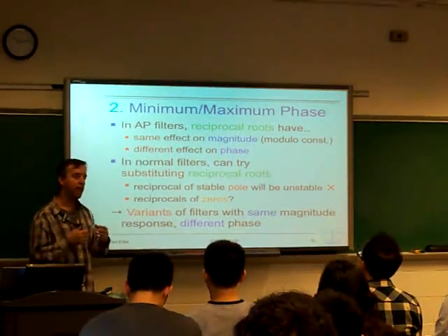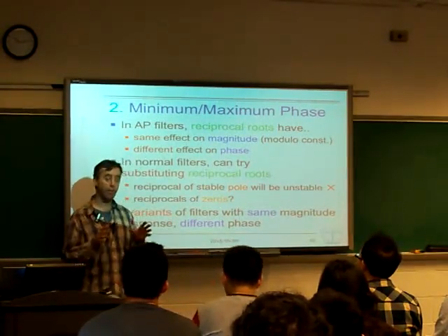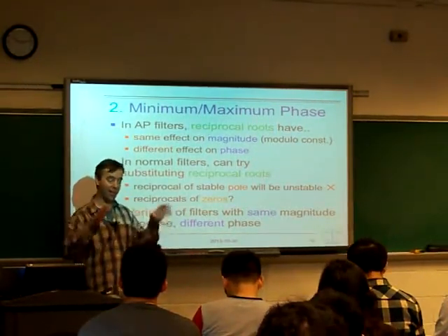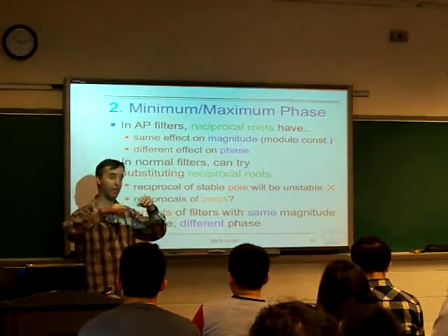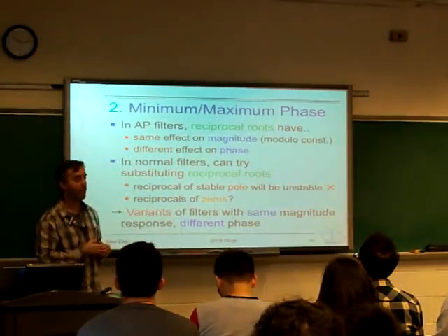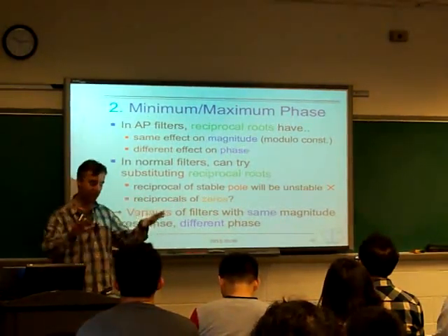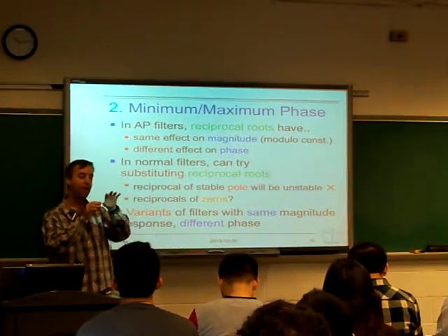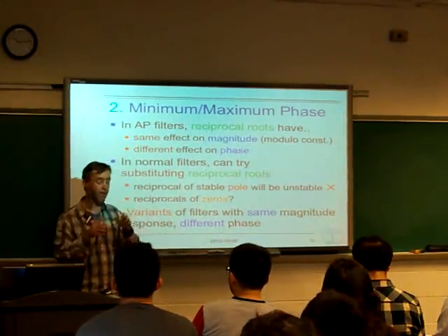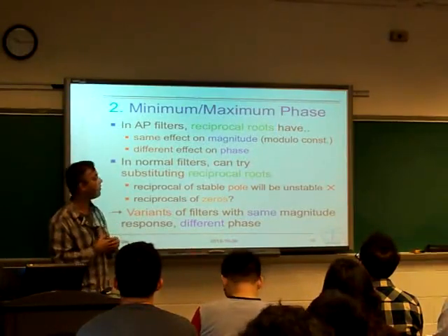Now, in the all-pass system, what was happening was we had poles inside the unit circle, which, if they were presented alone, would lead to peaks in the frequency response. Right? These in the closed form of the Z-transform has these poles sticking up. They're inside the unit circle, but at the unit circle, they still have these slopes that would then give us peaks in the frequency response. But outside the unit circle, we have these zeros corresponding to these holes in the Z-transform surface. And then right on the unit circle, the poles and the zeros are canceling out, so the overall net response on the unit circle, the frequency response, the Fourier transform, is constant. If you scale it right, it's unity for all frequencies.